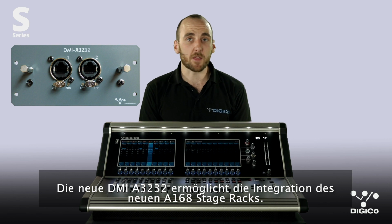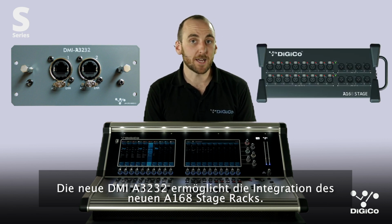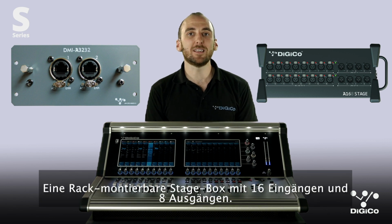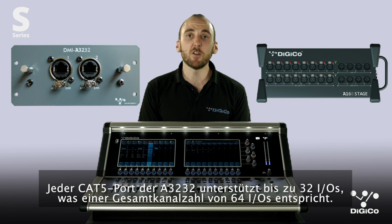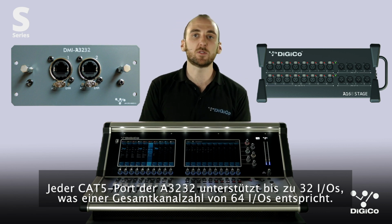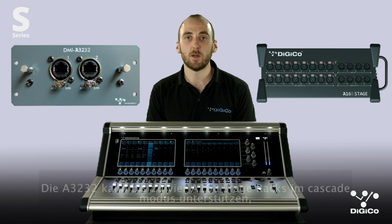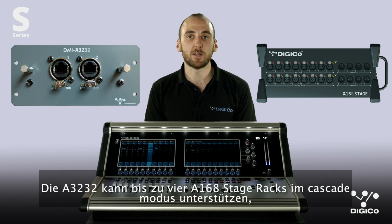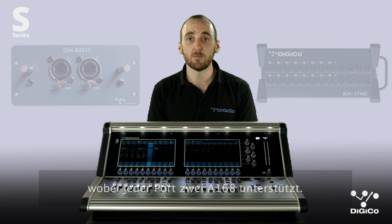The new DMI A3232 allows for integration of the new A16-8 stage rack, a rack-mountable 16 input and 8 output stage box. Each Cat5 port on the A3232 supports up to 32 I/O, for a total of 64 I/O. The A3232 can support up to 4 A16-8 stage racks in cascade mode, with each port supporting 2 A16-8s.